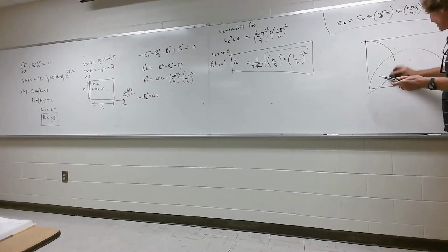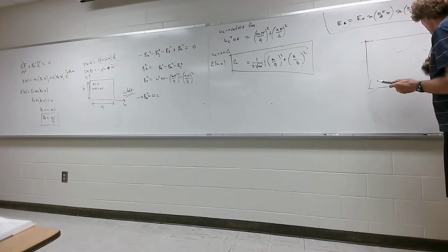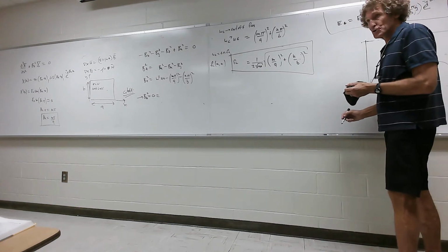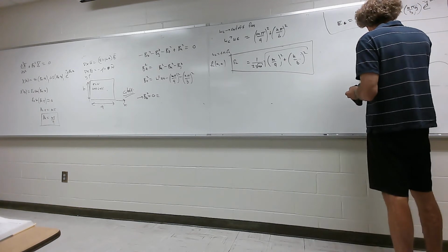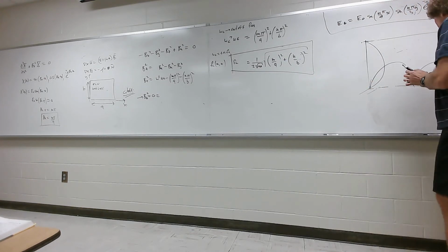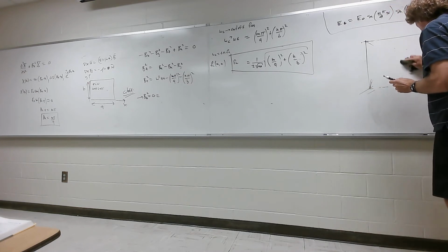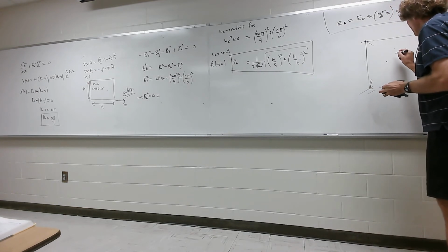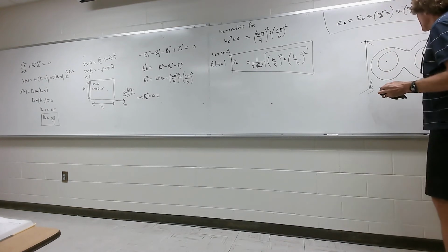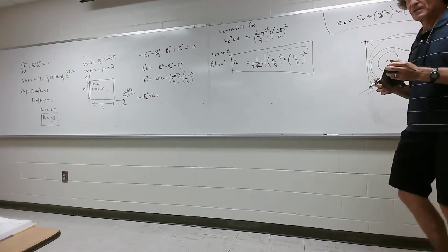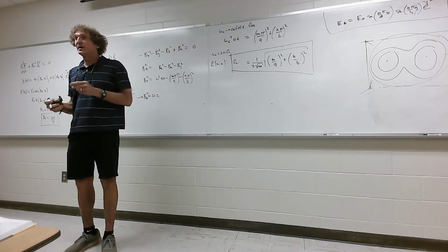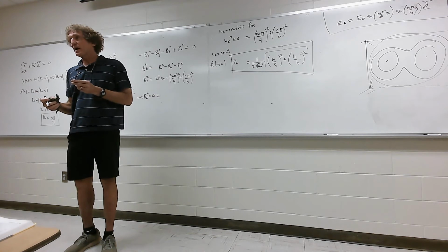Now, if you had the 2-1 mode, then you get this in terms of the energy. You get two relative peaks that way, one relative peak that way. You can almost see what's going to happen. Now you would have contours where you'd really have two centers, and eventually the thing would blend like this, but you basically have two modal centers. That would be the 2-1 mode. 3-1 would be 3 in that direction, 1 in the other, and so forth. But the higher the mode number, the higher the frequency.